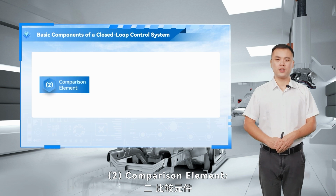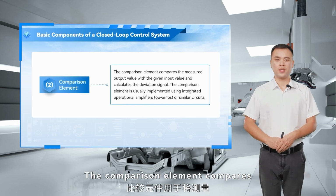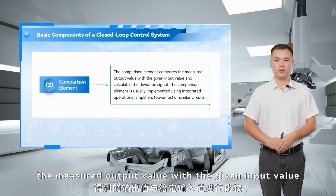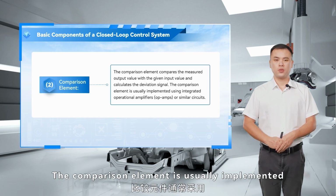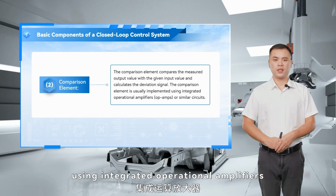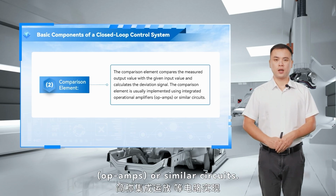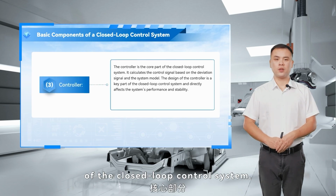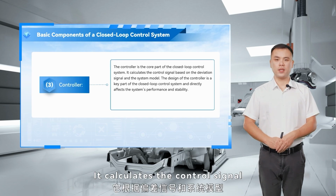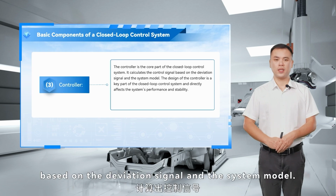2. Comparison element. The comparison element compares the measured output value with the given input value and calculates the deviation signal. The comparison element is usually implemented using integrated operational amplifiers, op-amps, or similar circuits. 3. Controller. The controller is the core part of the closed-loop control system. It calculates the control signal based on the deviation signal in the system model.